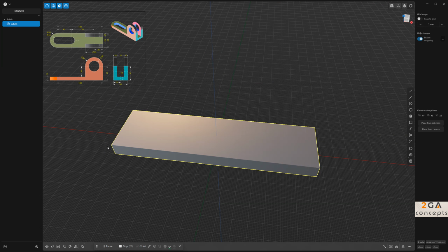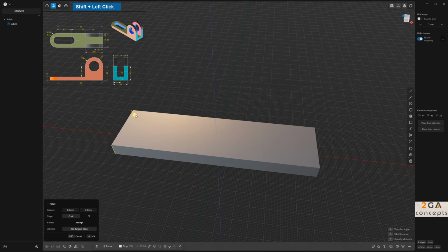So we can start to do the bevel there. So it's 20. So yeah, I've got everything selected here. That's for the selection control point. So it's 1 for vertex, 2 for edges, 3 for faces, and 4 for the body. So here I'm going to hit 2 to be in edge selection mode.